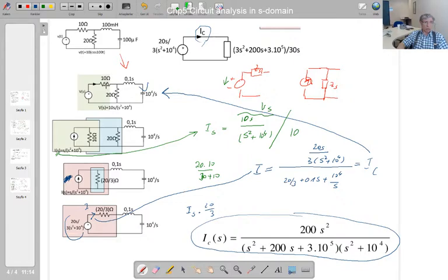So you know this element current, multiply by 10 gives you this element voltage. This element current I know, with the difference of sign, is the same as this independent voltage source current. So I calculated all the elements' currents and voltages by using this source transformation analysis technique.